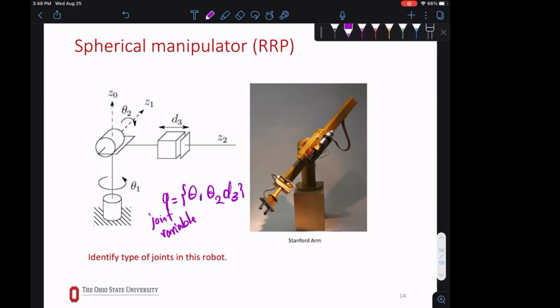So this must be a revolute joint, but this is moving in more than one direction. This is actually made of 3 revolutes. So we're going to break this down into 3 revolutes and decide which one is going to be 1, 2, 3, and we stick to it. We put a reference frame on it. They're all going to have the same rotation matrix because they're all moving together. It's a great question.